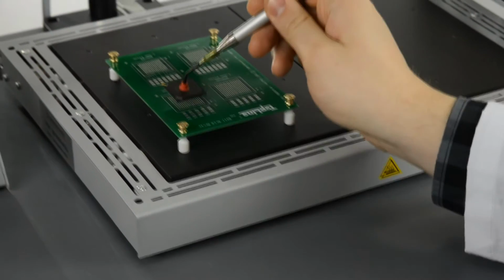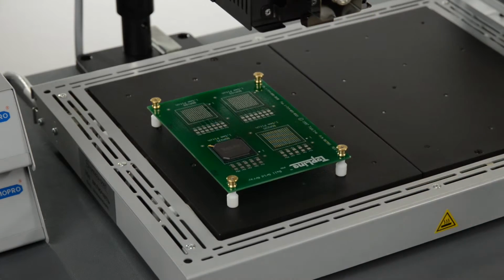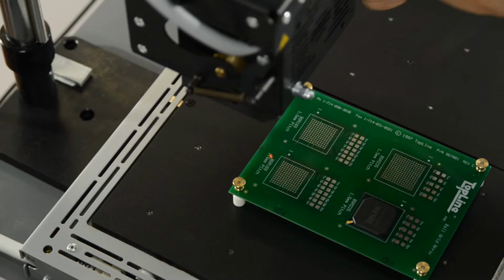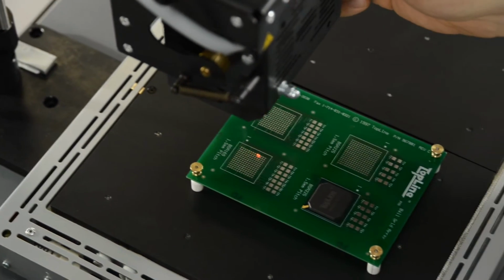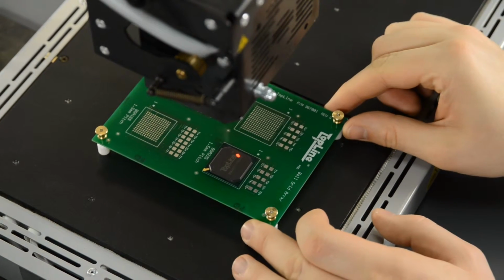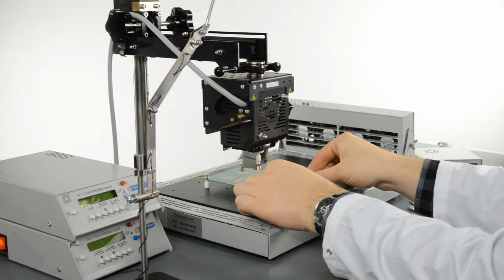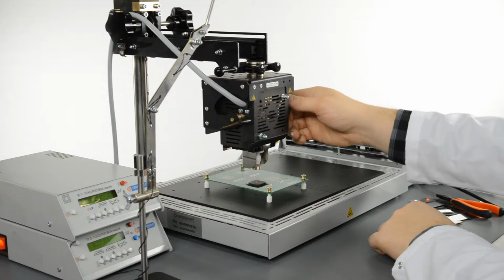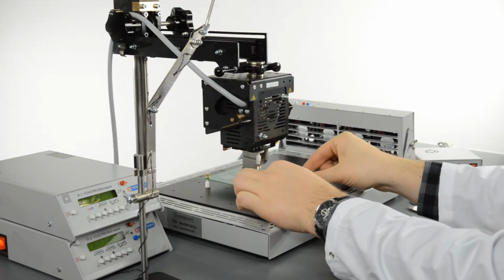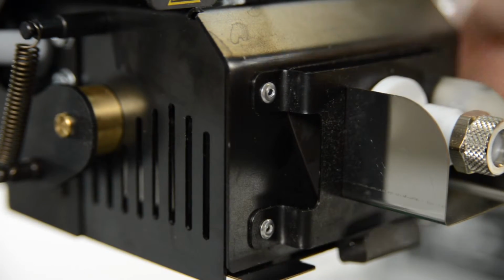Place the processed component on the contact pads by the method accepted at your enterprise. Move the top heater into working position. For that, turn the heater's head counterclockwise into laser pointer position and move the laser dot to the center of the processed component by sliding the holder's arm and rotating it around the central shaft. After the laser dot is aimed at the center of the component, fix the holder arm by tightening the fixing nuts and turn the heater head into working position, turning it backward, clockwise.